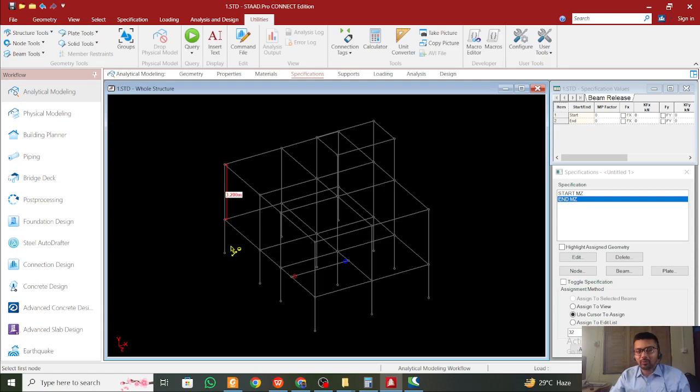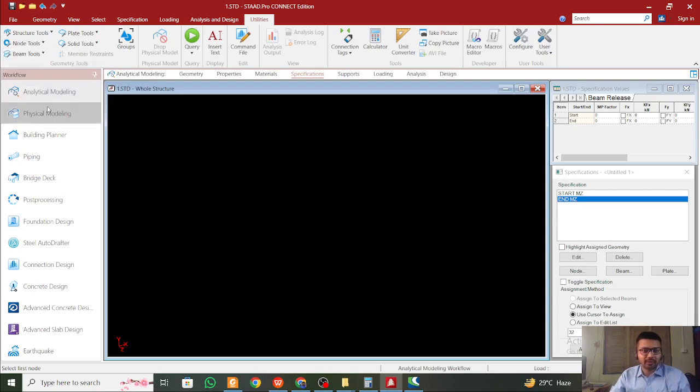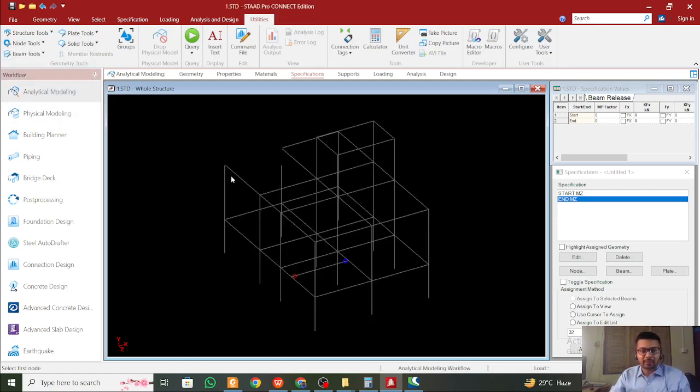So if you have taken the bottom coordinate, some people like to make the foundation coordinate 0, so you have to add this height. That's why I take the plinth coordinate as 0, so that's helpful. We'll go to node tools and remove the node to node distance here. I want to apply a diaphragm here, and obviously you can apply it in the plinth level also. Okay, let's apply diaphragm everywhere, but technically if we don't have a slab here, this won't act as a diaphragm. So let's skip the plinth level, but apply here and one here.